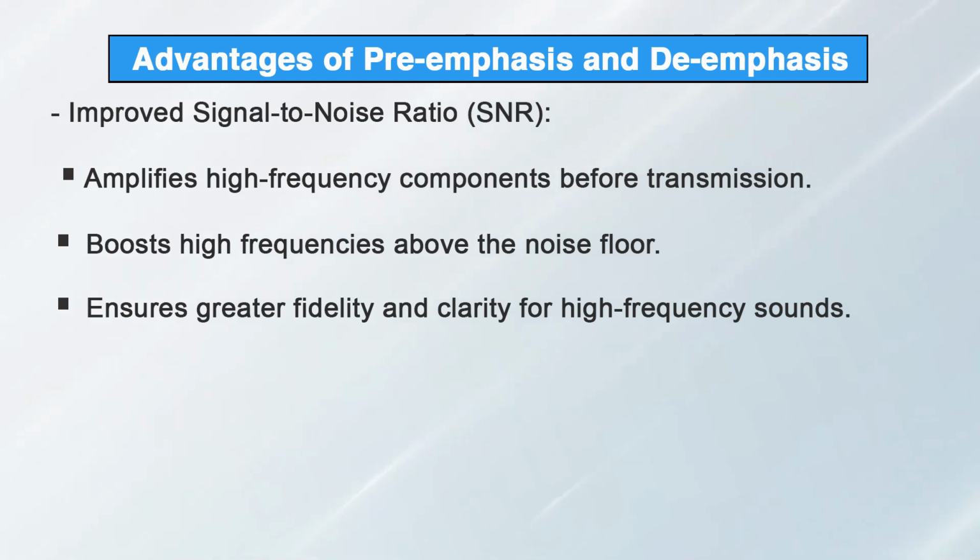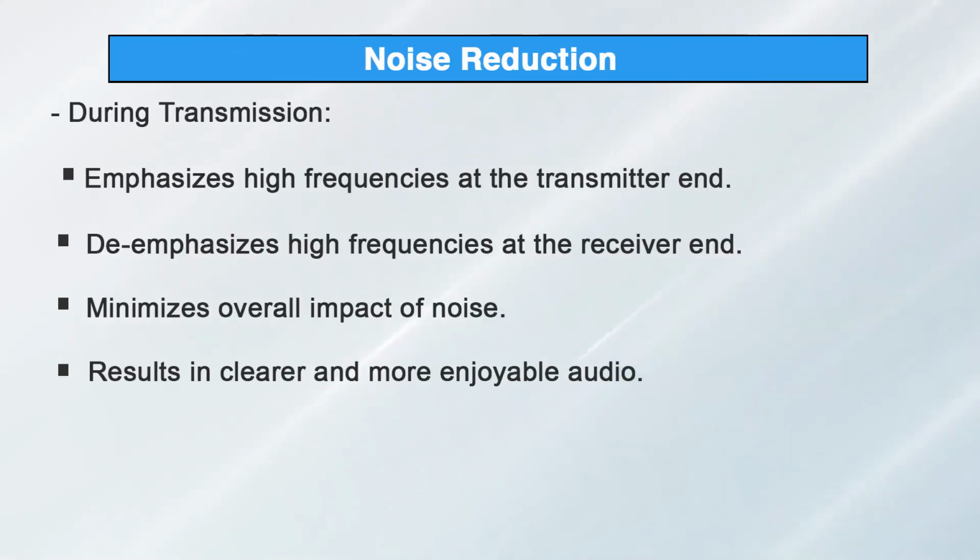and clarity. Consequently, the listener receives a clearer and more accurate audio signal, which is particularly beneficial for music and speech broadcast. Another advantage is noise reduction during transmission. By emphasizing high frequencies at the transmitter end and subsequently de-emphasizing them at the receiver end, the overall impact of noise introduced during the transmission is minimized.